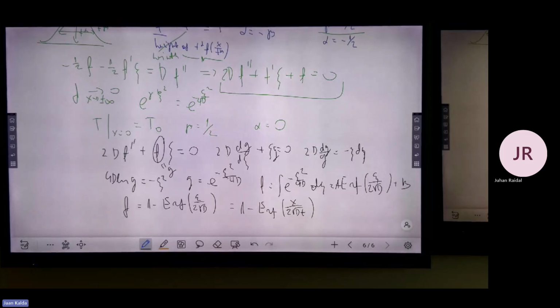And consider another situation where you have a plate which has good heat conductivity, and then beneath it you have something which has not that good conductivity, like metal on top and some non-metallic material below. Then you start heating at one end of the plate. Heat will very fast propagate along the plate, but it will be lost across the plate.